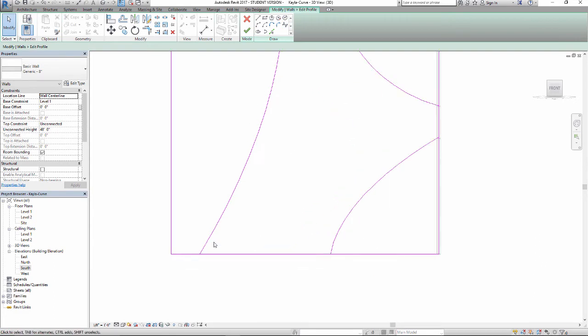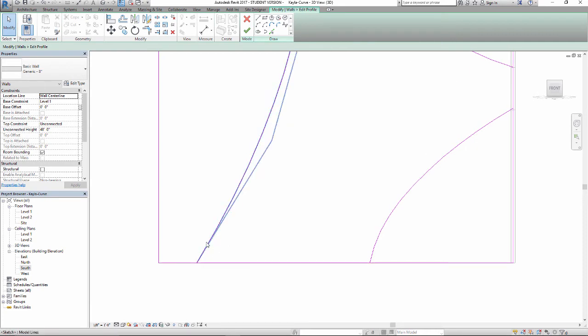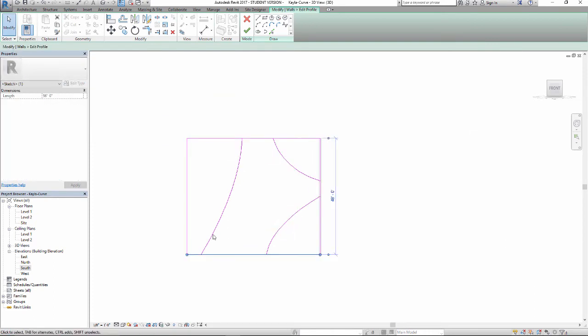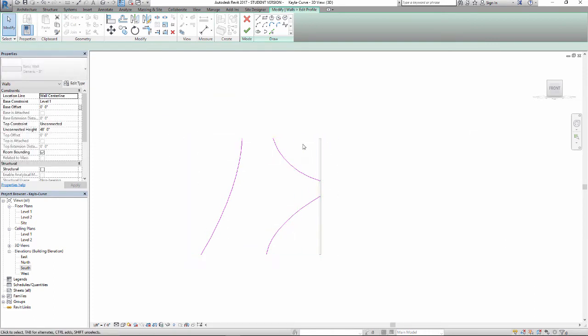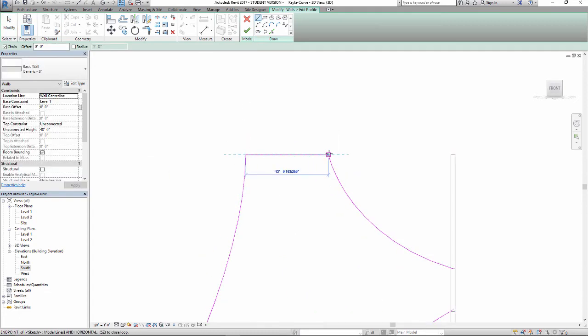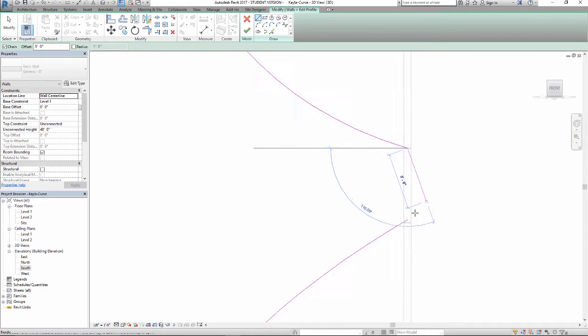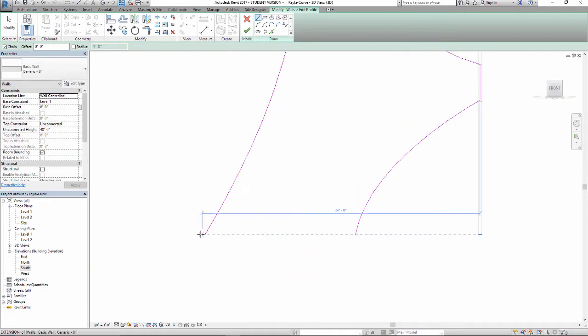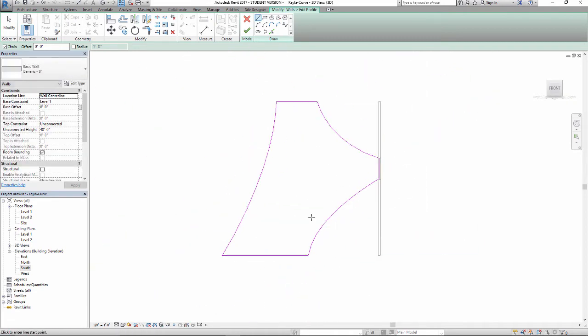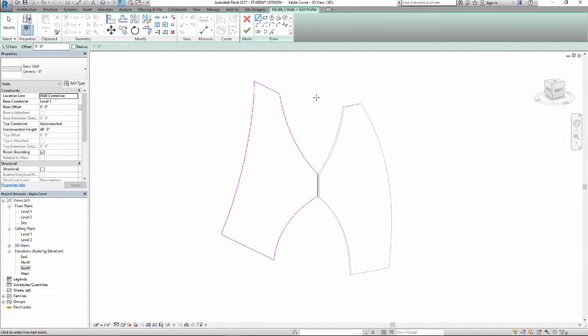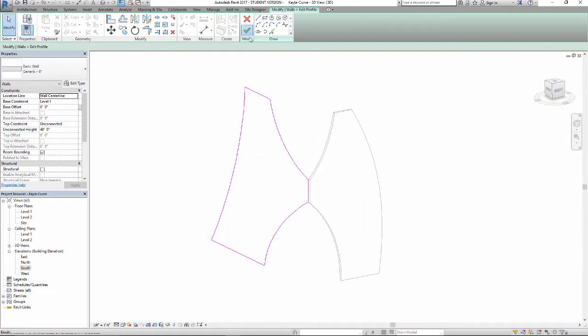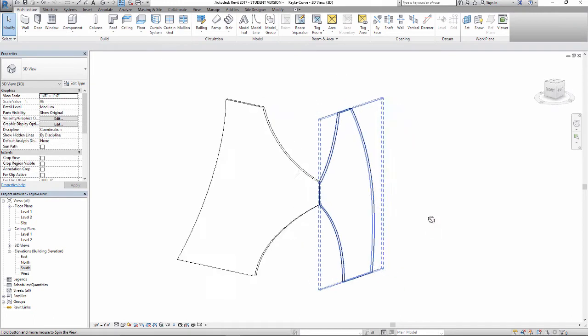And with the spline tool, you've probably already realized if you've worked with Revit, I cannot run the trim command to reattach something to a spline. So I need to simply come back in and erase all of those edge lines and replace them with new lines. So not too much to complain about, really. Just go back and do it quickly. So I have this as the new profile for my wall, which gives me this kind of result.